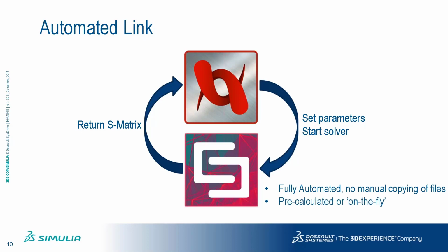You can either run this on the fly. So for a particular parameter combination, you just say, I need the results for this, and then you just trigger it and it comes back. Or, and this is especially interesting if you're looking at a large number of calculations, you can pre-calculate a number of combinations in advance overnight or so, because photonic 3D and multiphysics simulations take longer than a typical simulation would in the design suite, just because of the higher complexity of a full wave 3D simulation.